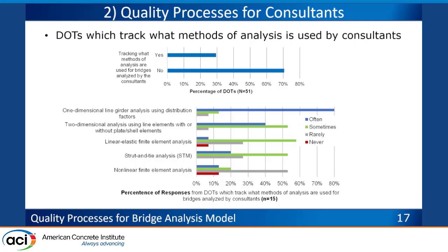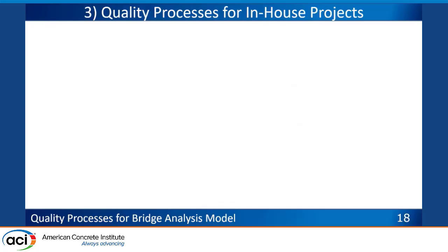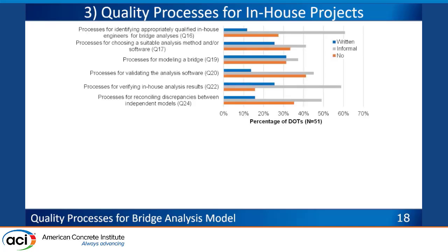Linear elastic finite element is also not very commonly used, but the most common is one-dimensional line girder analysis, two-dimensional analysis. So these are the most often used type, but finite elements are a little bit less used by consultants. So the final part of my presentation will look at in-house. These are the bridges analyzed, designed in-house by state DOTs, and we asked 6 questions.